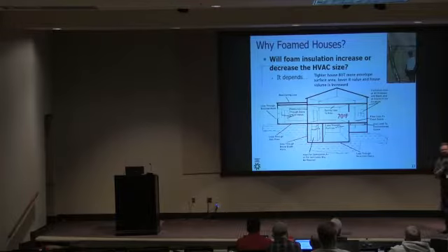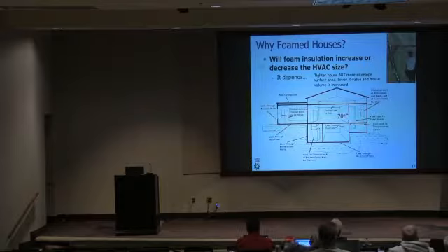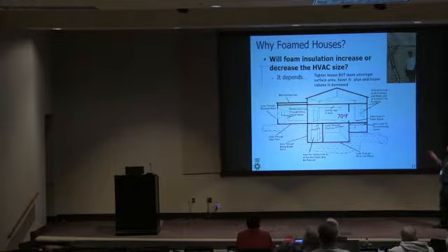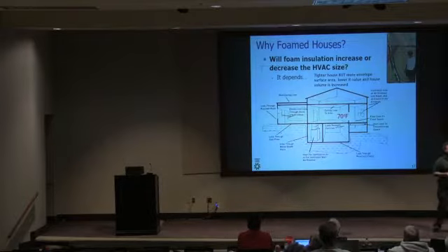So the law of diminishing returns says once you get to about an R20, you've dealt with so much of the conduction that to spray another R10, that's 50% more cost, is not going to get you a significant reduction in heat conduction through that assembly. So R20 is about the standard spec, and it's an expensive product. So they tend to do about an R20, so you're going to have a lower R value, and you're going to increase the volume of the home.